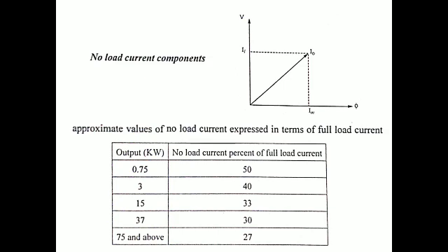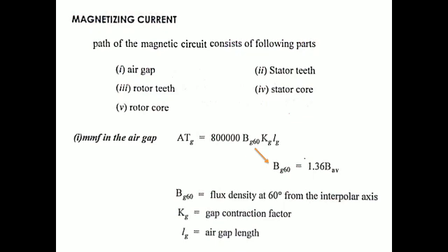Next, in this area we have two titles, the losses and the magnetizing current. Let's see them one by one. Now go with the magnetizing current, Im. To calculate this value, we have to consider the flux. This is the current which produces the flux. That flux, in terms of flux density and H, is in terms of mmf, so we can directly relate them. This current is found by directly linking the mmf values of different portions.